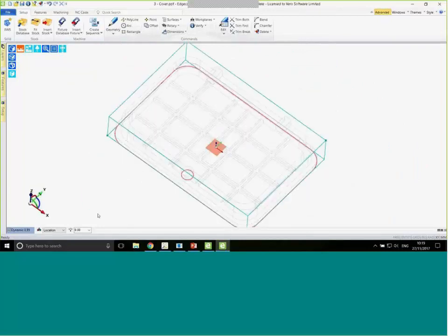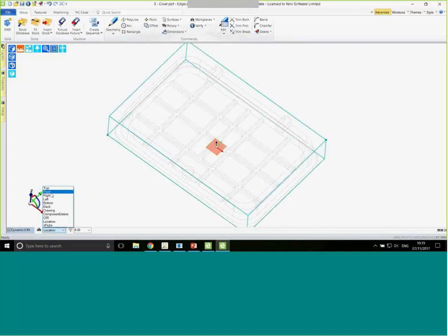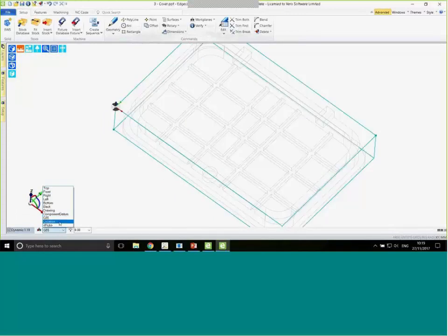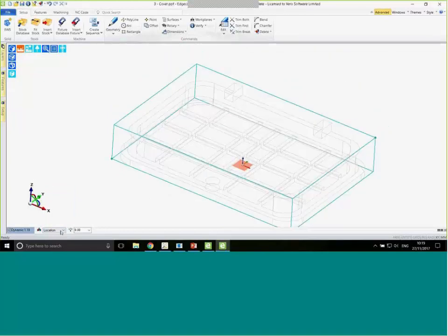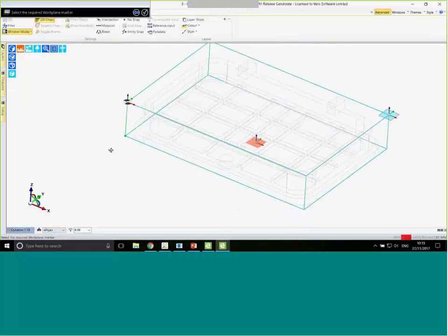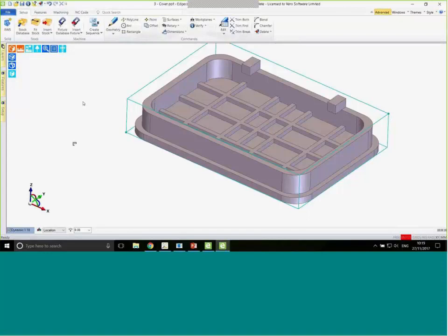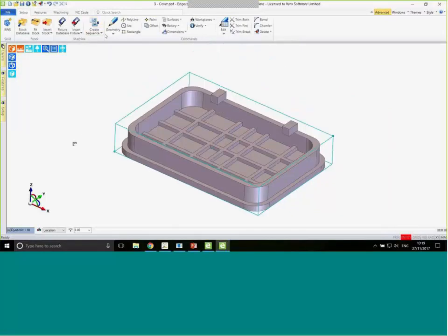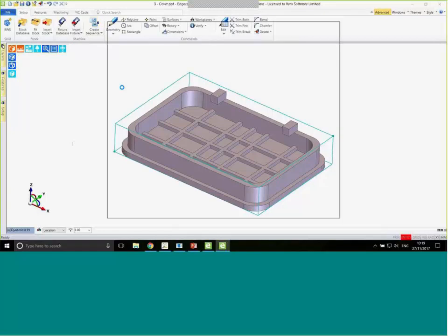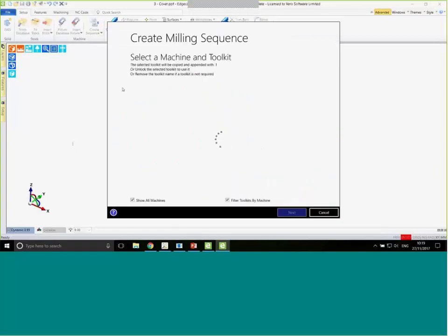Now you'll see a different appearance of datum. So we've got a component datum in blue. We've got machine datum, which you can see is the traditional datum marker. And we've got a location datum. And what we're simply doing is flagging up the different types of datum that users use generally day to day inside Edgecam. Although on a simple part like this it maybe wouldn't be too important, you imagine a user with multiple parts being loaded into, say, a tombstone or a multi fixture.